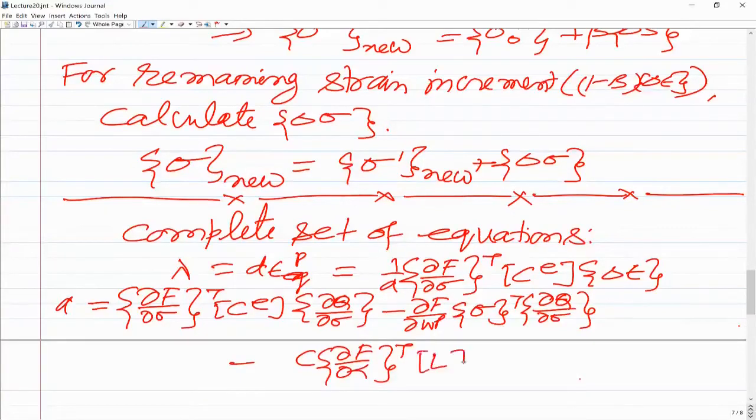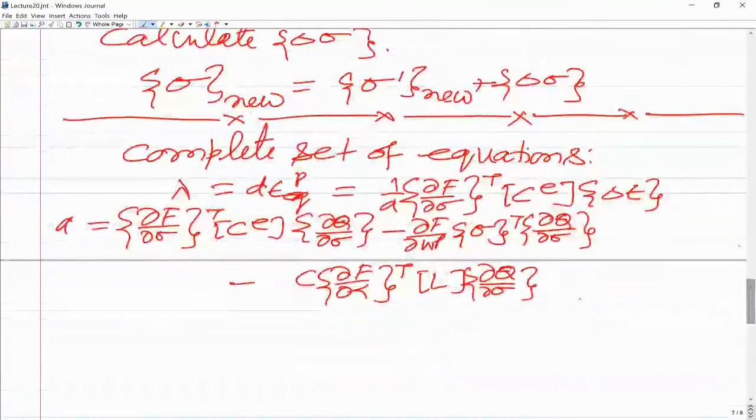That is, there can be kinematic hardening, or they can be isotropic hardening. So if isotropic hardening is there, the third term will not be there, and if kinematic hardening is there, then the second term will not be there, the third will be there. So this is del q by del sigma. So this is how you calculate the expression for delta epsilon equivalent p.